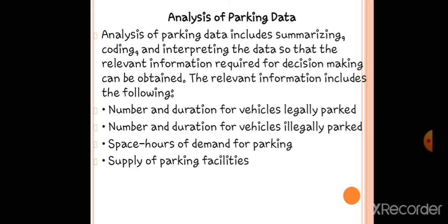Analysis of parking data. Analysis of parking data includes summarizing, coding, and interpreting the data so that the relevant information required for decision making can be obtained. The relevant information includes the following: number and duration for vehicles legally parked, number and duration for vehicles illegally parked, space hours of demand for parking, supply of parking facilities.